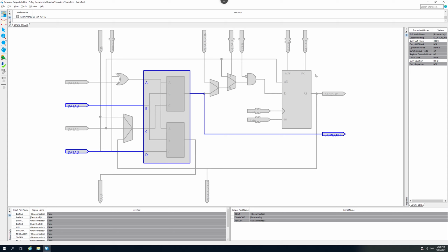Now, if you can convert this to binary very quickly in your head, and then think of the full truth table, you can work out what it's implementing, but it's easy to look down here to see the mathematical equation for it. Don't ask me why they don't have an OR sign here, they have a dollar sign instead, but the principle is this tells us that the output of the LUT is going to be the input B ORed with the input D. You can also deduce that from how it's configured. This is the number that's actually written into this logic element's lookup table to make it do its job.